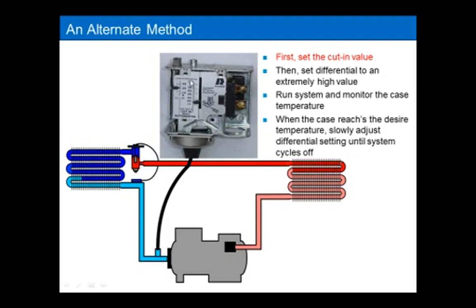These scales here that are used are not very accurate all the time when it comes to adjusting the exact cut-in. So I would double-check these scales by attaching your own pressure gauge to the system and watching at what pressure it cuts in at, not based on what the scale says, but with your pressure gauge. So use your pressure gauge as the instrument to set the cut-in.